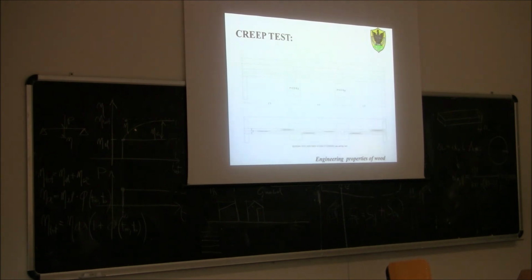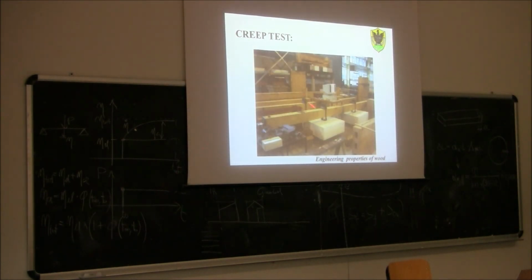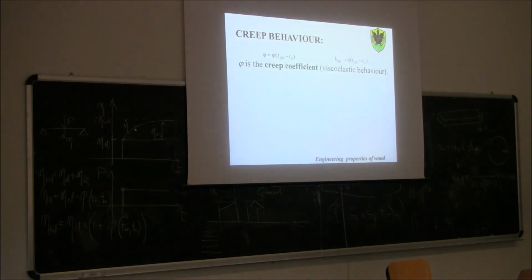Now, how do we do this creep test? This is an example of a creep test that I carried out 10 years ago in New Zealand. A piece of timber, with two blocks of reinforced concrete hanging on the beam, and here a potentiometer to measure the increase in deflection over time.